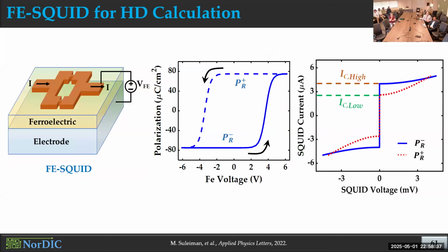So let me go back. So here, if you see, for the Hamming distance, we need to operate at this resistive state. But here we only use 5 microamps of current to go to this resistive state. But if we increase the current, that will have higher power consumption, but that will give us better distinguishability between these voltages that we get for different degrees of mismatch. So if we go to a higher memory array, we can use that to get better distinguishability. So with more power, you would get more noise margin. Yes, yes, more distinguishability. That's how I'm interpreting what you're saying. Yes, yes. Okay.